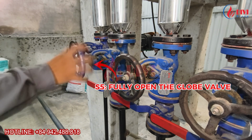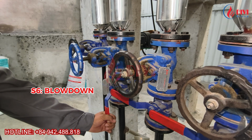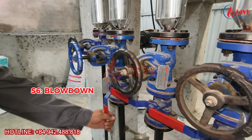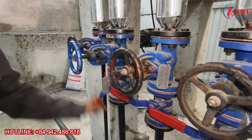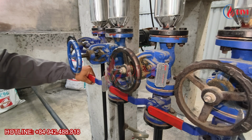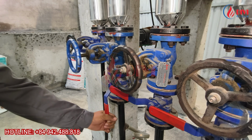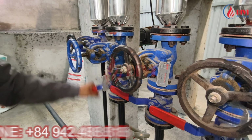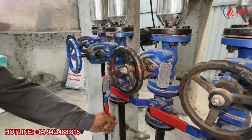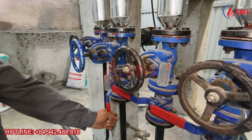Step 5. Fully open the globe valve. Step 6. Perform blowdown. Execute blowdown by quickly opening the ball valve in short bursts. Each burst lasts 3 to 5 seconds, then close it quickly. This rapid open-close action helps dislodge scale near the blowdown outlet. When reopened, the deposits are forcefully expelled. Typically, each blowdown cycle consists of 5 to 10 bursts.